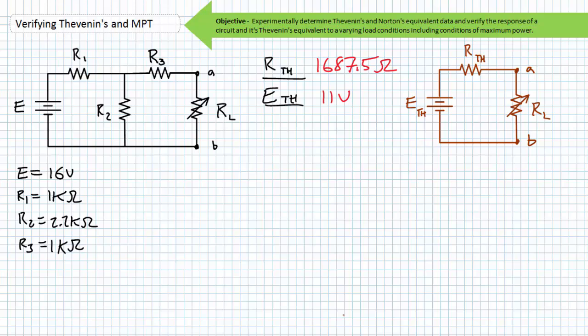However, it is notably easier to solve for desired electrical quantities, being a simple series circuit. A single application of the VDR could be used to solve for the voltage drop experienced by any load. Ohm's law and the power equations can be used to solve for current and power experienced by any load.